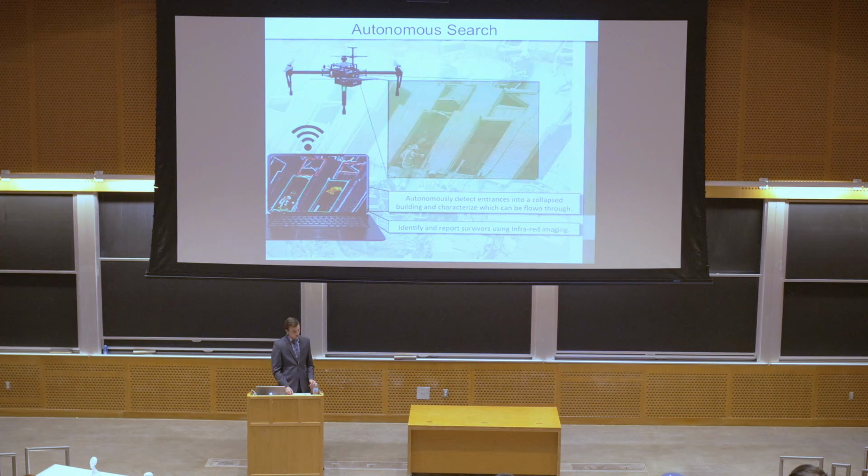The LiDAR sends out a laser in a 270-degree scan, and this light reflects off of surrounding objects and is returned, from which we can get a distance value. The result can be visualized essentially as a 2D horizontal slice of the environment in the column of air that we're in. From this information, we are able to accurately determine distances to walls and nearby objects, and we attempt to classify these and look for the largest objects in the area and possible gaps between them that we may be able to traverse through.